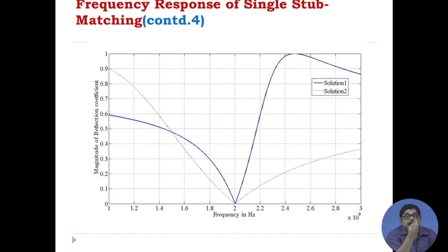Another distinction point is the size of the stubs, etc. he is getting, because these two solutions will have different lengths of transmission lines and different lengths of stubs. Now, getting larger may be problematic, and getting very small also may be problematic because of mechanical construction, etc. So, at that time you will have to decide based on other criteria, but you have this scientific analysis behind you.